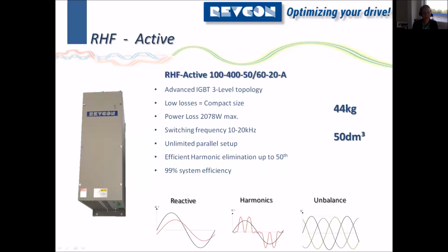Okay. Do you have any information about these applications, about the input current? I would expect that the laser cutters typically have a DC input, so they will have a huge harmonic distortion. I'm not sure if this is purely a harmonic problem, but these problems that you described, burning cables, capacitor bank blowing up, I would expect can be very much related to harmonic problems. So at least I would make a measurement on this equipment and see what the voltage distortion is. So you need to find someone who can do this in your area. Which area are you from?